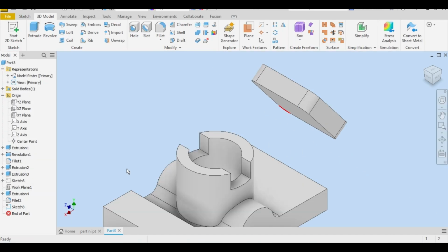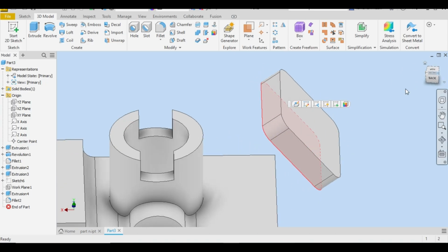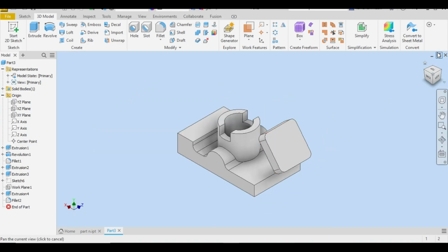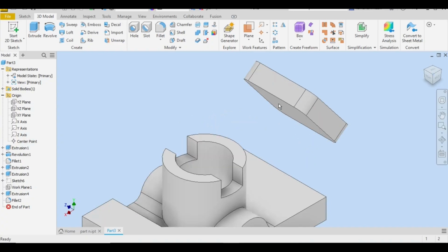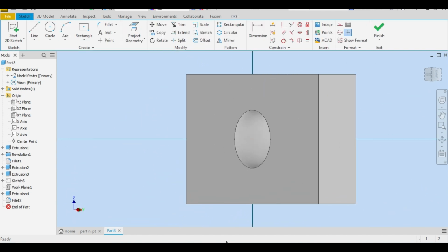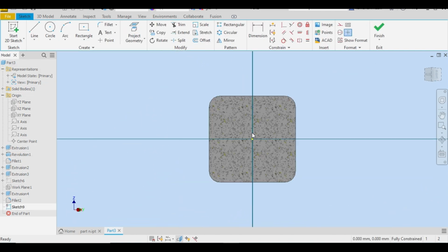So let me delete this sketch, create sketch at this face bottom. Let me rotate, create sketch here, so we can join to the surface. Slice graphics, so press F7. Okay, we can see it. Select a circle, give dimension.